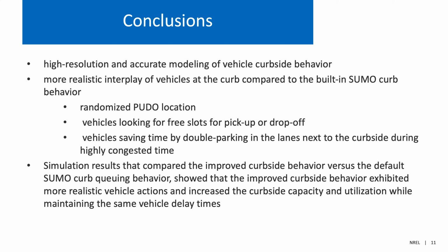And then last, simulation results comparing the improved curbside behavior versus the default behavior show that the improved curbside behavior exhibited more realistic behavior and increased the curbside capacity and utilization while maintaining the same vehicle delay time.